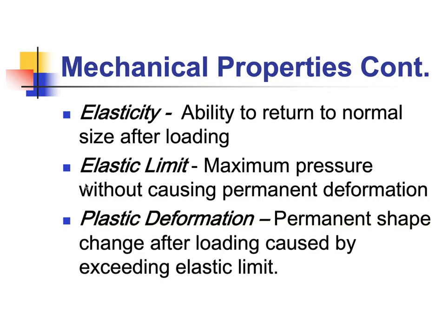Okay, so the elastic limit is on that diagram, also called the yield strength. It's basically where that linear portion ends, and we no longer get elastic deformation. A mechanical engineer will design up to this elastic limit. Now, they usually don't want to get too close to it, because if someone does something stupid, like drive something too big across a bridge or something like that, it could fail. So what they do is they use a safety factor, maybe 2, maybe 10, so that the bridge or whatever structure is stronger than it needs to be.